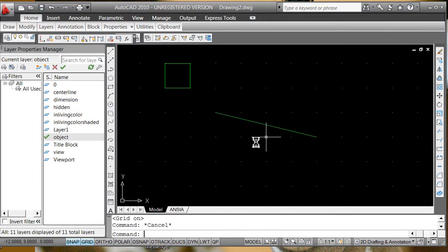I will point out, finally, that as we make this block, I may have misspoke slightly. If in fact the blocks that we're going to make in here have a snap point in the middle of this line of 1, we're going to have a hard time connecting it up along a grid.